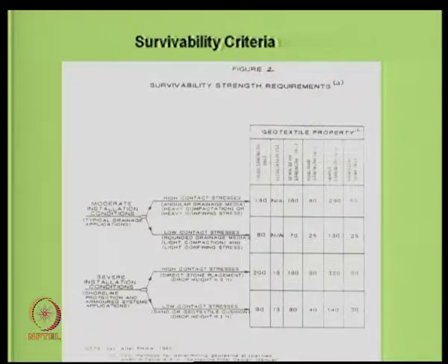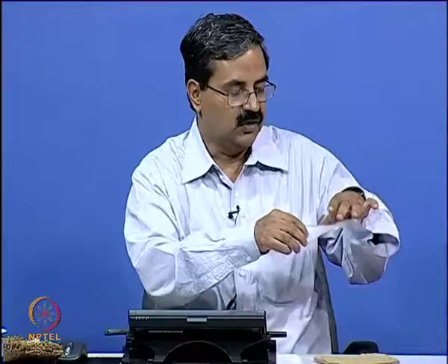Why it is required is that, like I can show you those properties. These are all geotextiles, and there is a parameter called grab strength. Grab strength is the load at which it can fail. There are other parameters like elongation, seam strength, puncture strength, and tear strength. You have standard test procedures: what is the load required to tear it, and what is the load required to penetrate it? You measure the diameter, and what load can create a particular diameter.